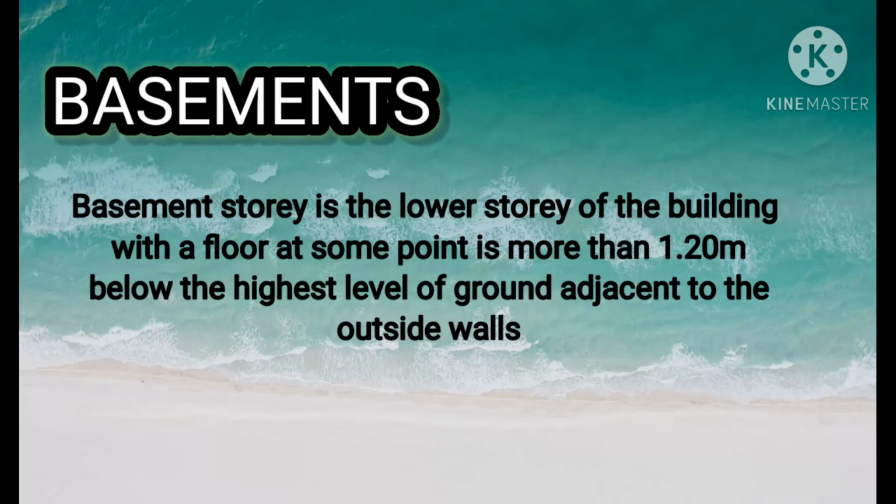This section on basements is concerned only with basement stories that are below ground level. The structural walls of a basement below ground level are in fact retaining walls, which have to offer resistance to the soil and groundwater pressures, as well as assisting to transmit the superstructural loads to the foundations. It is possible to construct a basement free of superstructural loadings, but these techniques are beyond the scope of this book.